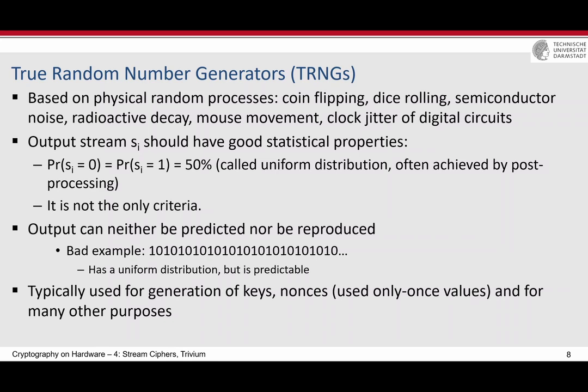PRNGs you can build with normal hardware that we are learning, like VHDL or Verilog, and then you can generate a random stream at very high speed. For example, if your circuit allows 500 megahertz, you can generate 1 bit per clock cycle, that fast. But TRNGs are usually not able to generate at 500 megabits per second. This is almost impossible for the TRNGs that are available now.